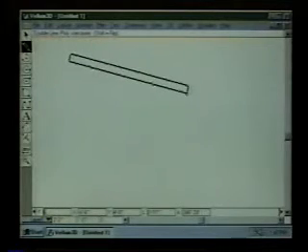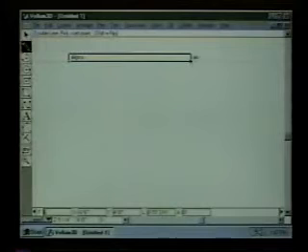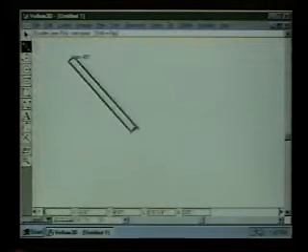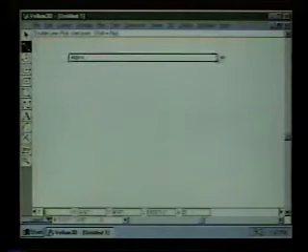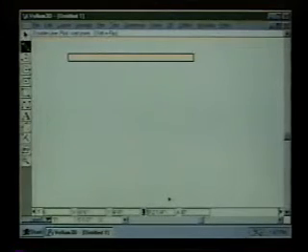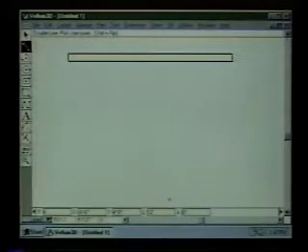And it gives me a wall object, and again, because of the drafting assistant, it snaps right on horizontal and 45 and vertical and so on. And when I draw this wall, initially this wall is 9 feet long, 2 1/4 inches. Well, I might know it needs to be exactly 12 feet, so I can type in 12 with a single quote for foot, so 12 feet. When I hit enter, it goes to exactly that size.